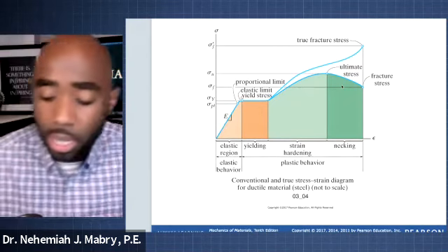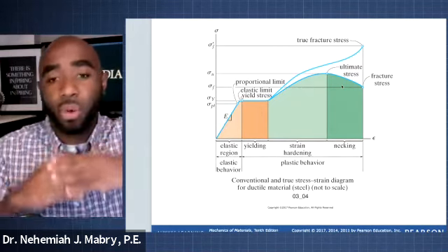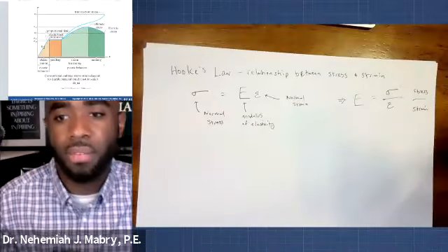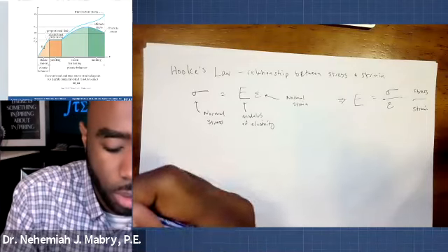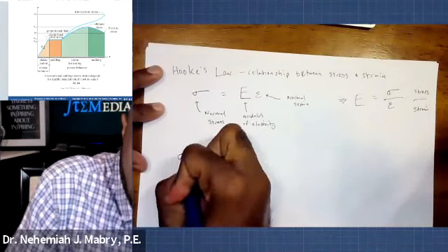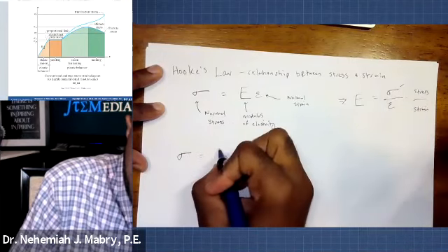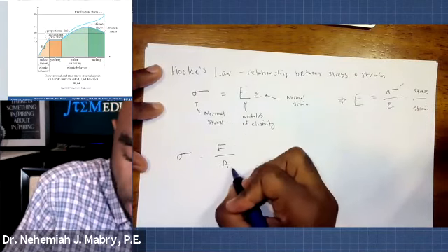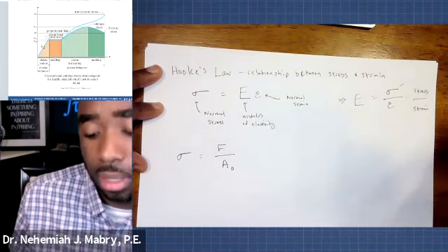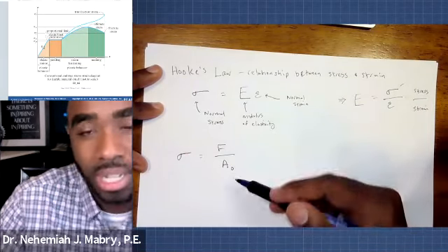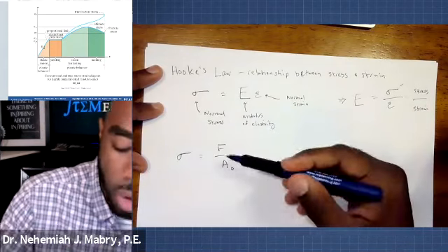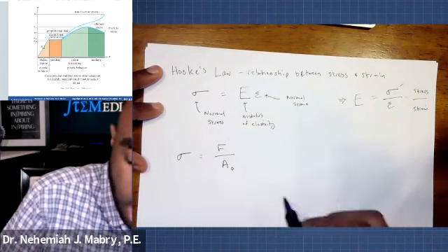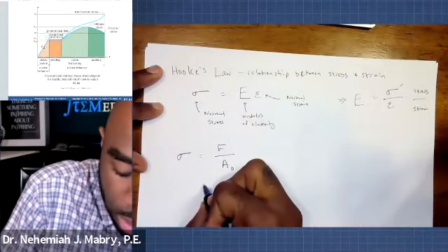So what does that mean? That means the value underneath the force term, let me show it to you. Recall that stress, at the top of this equation, is force over area. And just to be clear, the engineering stress always keeps the initial cross section. It's not changing as time goes on. Therefore, as the load increases, with the area being constant, stress is going to be directly proportional. However, when it comes to true, versus engineering,